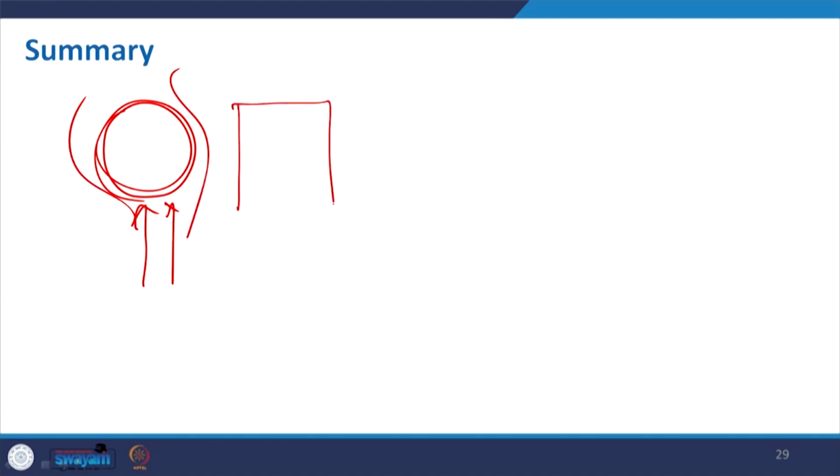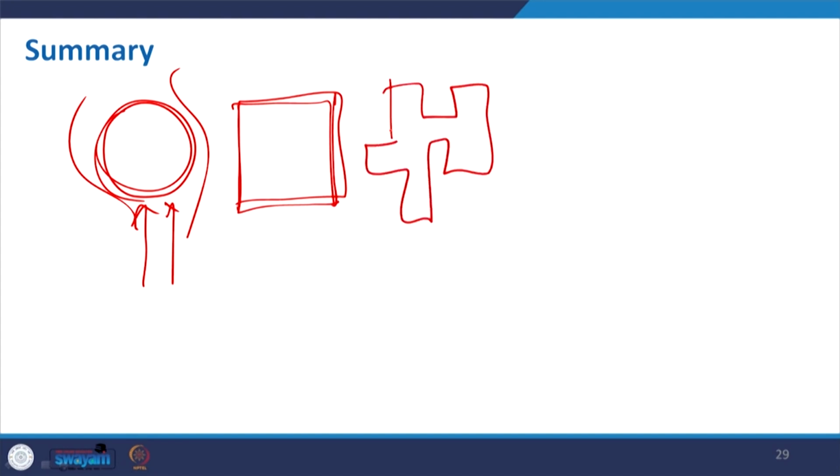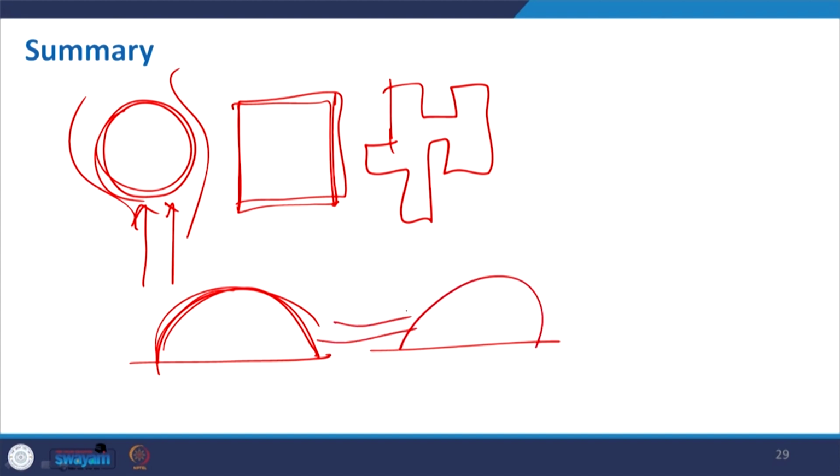If not, try to make the building symmetrical or squarish in form, not a very irregular or zigzag pattern, which may be more prone to vulnerable situations with heavy load. In the case of the elevation, it is preferred to have an aerodynamic shape. It may be a domical, semicircular, or egg shape depending on the prevailing wind direction. This may be done, especially for high rise structures, and we will discuss that in detail.